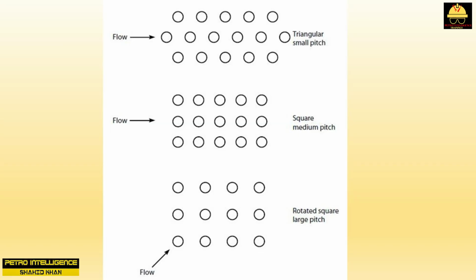Selecting proper tube pitch. From a theoretical heat exchanger perspective, the triangular tube pitch shown in the picture is best. The term pitch refers to the geometry and distance between the holes drilled into the tube support baffles. A triangular pitch means the holes are drilled in the pattern of a 60-degree equilateral triangle. For example, we might have a 0.75-inch tube OD on a 1-inch triangular pattern.